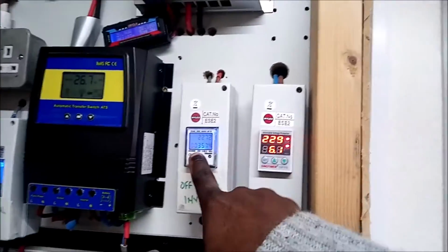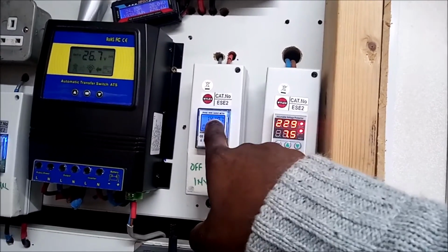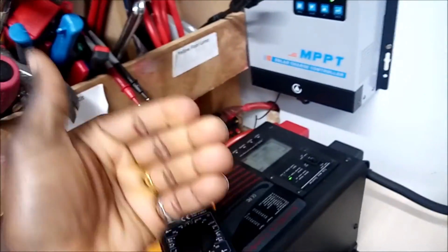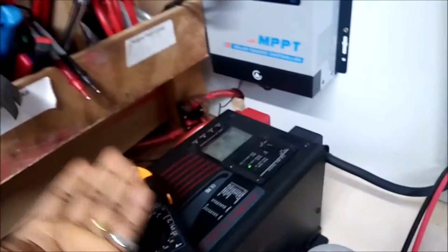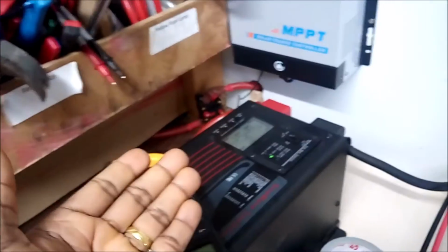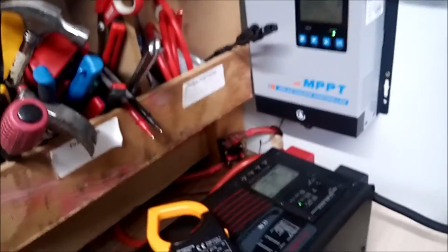So basically, what I would say is this: always divide the power that you're consuming by your battery system voltage. That is when you can determine how much current will be coming out of your battery. Now, if you have a 12-volt system, it's going to be totally different, because you'll be pulling a lot of current to invert it and give you energy for your AC appliances.